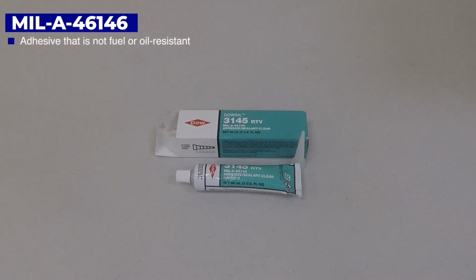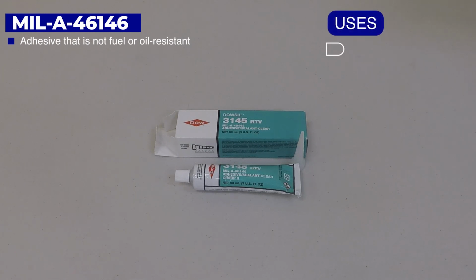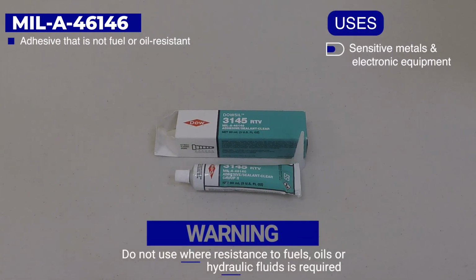Miltech AlphaTech 46146 is an adhesive that is not fuel or oil resistant, also a convenient sealant for use with sensitive metals and electronic equipment. Do not use where resistance to fuels, oils, or hydraulic fluids is required. For additional information regarding types and groups of adhesives, refer to your NAVAIR 01-1A-509-2, Table 7-1.